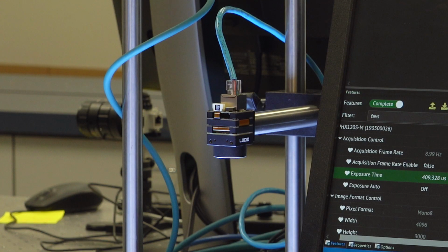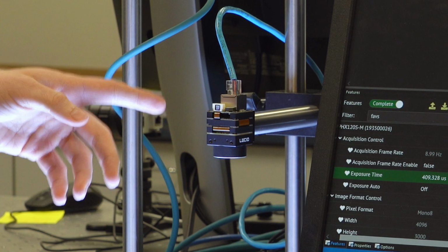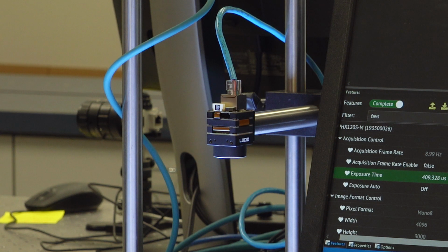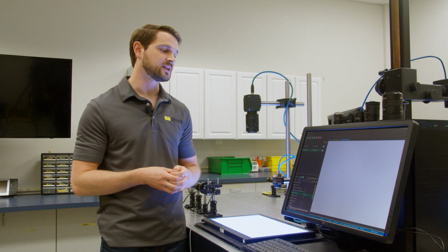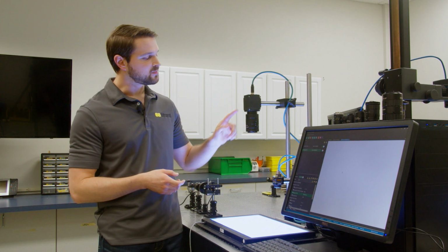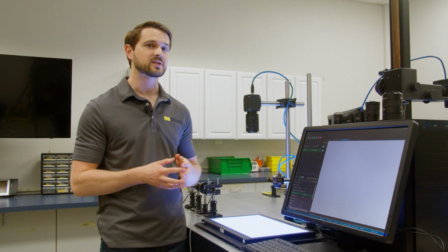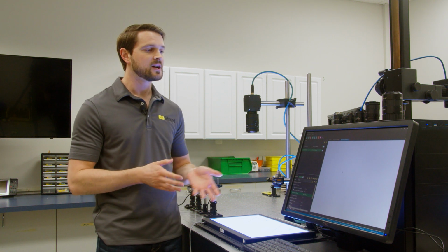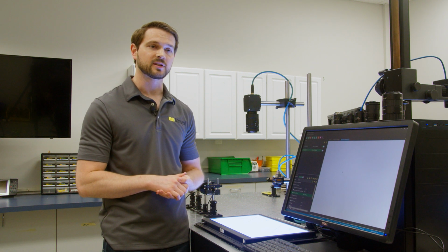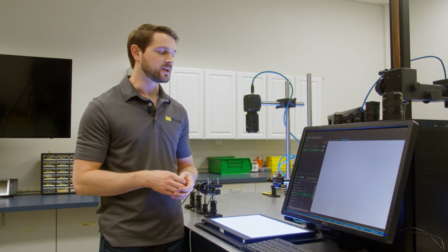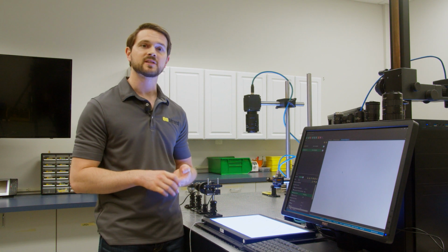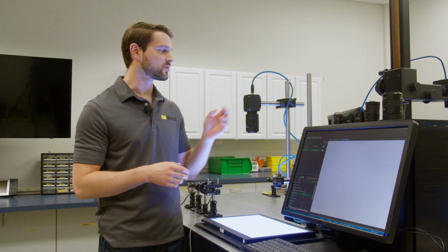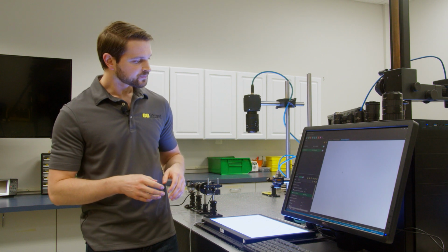The little camera that we have down here is the Lucid Vision Labs Phoenix camera. This has an IMX304 in it. That is a 1.1 inch sensor format, and it has a 3.45 micron pixel on it as well. So you'll notice the pixel size between these two cameras is the same. That's actually going to be important for one of the things that we're going to cover during this demo. I'll make sure to bring that point back up later. This sensor has a diagonal of 17.6 millimeters, so it's much smaller than the 32 megapixel sensor here.